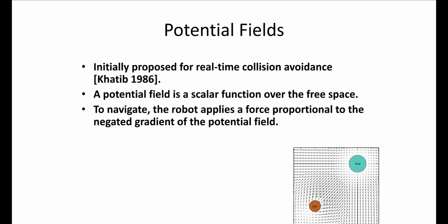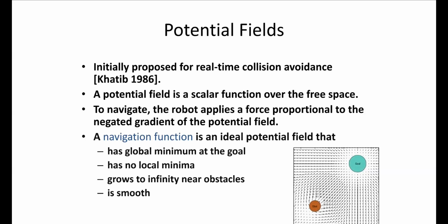I can look up the value where I'm at, and then look up all the neighboring values around me and just pick the direction with the greatest difference. So I could just empirically calculate a gradient that way, and that'll get me to roll downhill. All of this is going to be defined by my navigation function, right? The navigation function is something that creates those arrows. That's what I'm going to be using to figure out which direction to go.